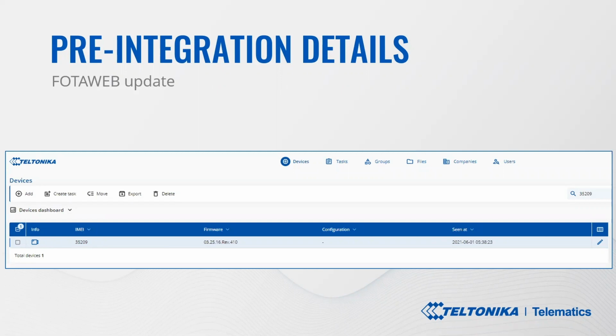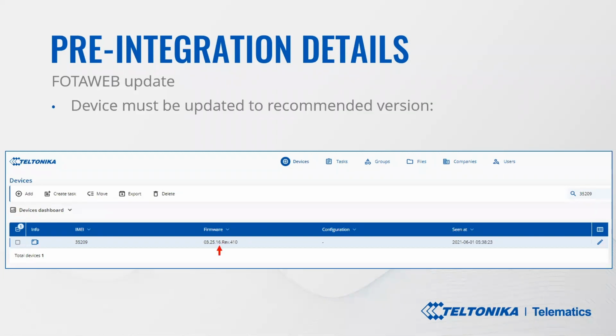To begin with the CAN unit software update, our Teltonika tracker must be running the current recommended FMB 140 firmware version. Specified here is 03.25.16 Rev 410. This is a base version of firmware used for FMB 140. Also, other firmware versions based on this branch can be used, so any newer versions that are already released.